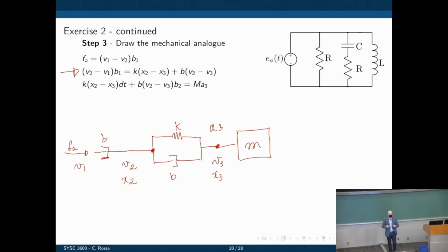Okay, and once again, now you might be confused. Why is this damper now positive? The other one was negative. Now we need to really analyze the mechanical system and figure out if the way we represented that is correct or not. And this one, indeed, if the force is coming from the right, the force of the damper plus the force of the spring are accelerating the mass. They're both positive. Whereas in the other case, the damper was opposing the mass and was negative. So everything was opposing the mass, the speed, and it was negative. So everything makes sense.